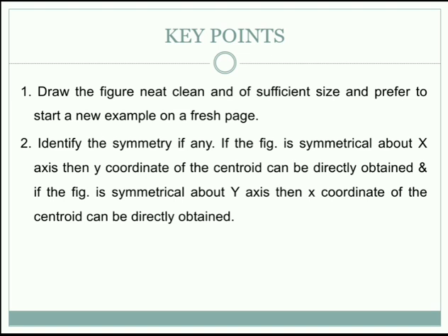Vertical centroidal axis. Now in such a case, the horizontal component of the centroid, that is x bar, can be directly found. So this thing you have to remember. You have to identify the symmetry in the figure.